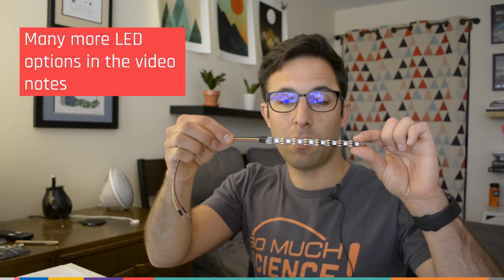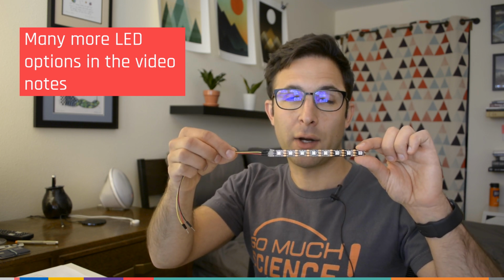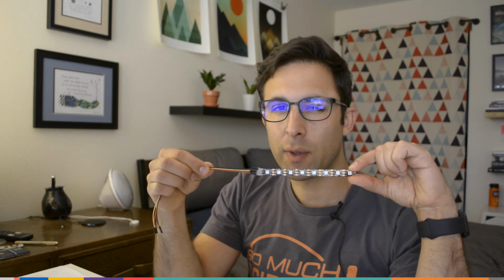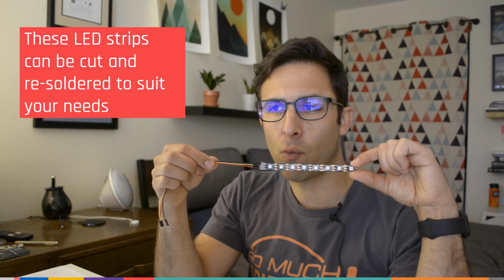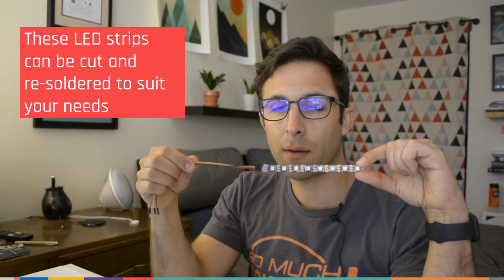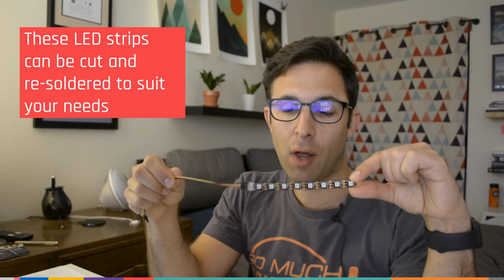The other thing you need, obviously, are the LEDs, and so this is what it'll look like. LEDs being operated by an Arduino without an external power supply, you can only get up to about 8 LEDs. If it was 8 LEDs emitting white, which means all red, all green, all blue, full on, they draw as much current as the Arduino is able to supply. So if you go any bigger than this, you need to get an external power supply, but we'll cover that another time. So I have 8 here so that I can power it with the Arduino.